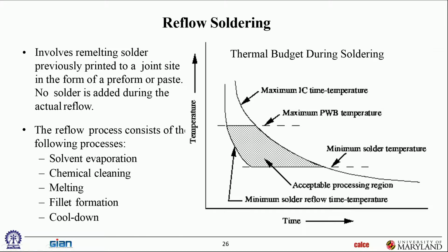The other big part of the reflow is the flux that is in the paste is activated during that pre-reflow. That means before you get to melt temperature, you want to activate the flux so it reduces all the oxides. Okay? So again, it has to be long enough, not too long. If it's too long, the flux is going to get completely consumed, and then there's nothing left during the actual melt, and it'll reoxidize instantaneously. So that preheat cycle is also extremely crucial.